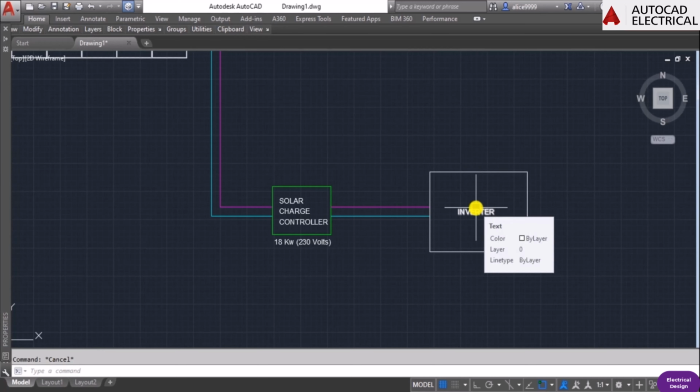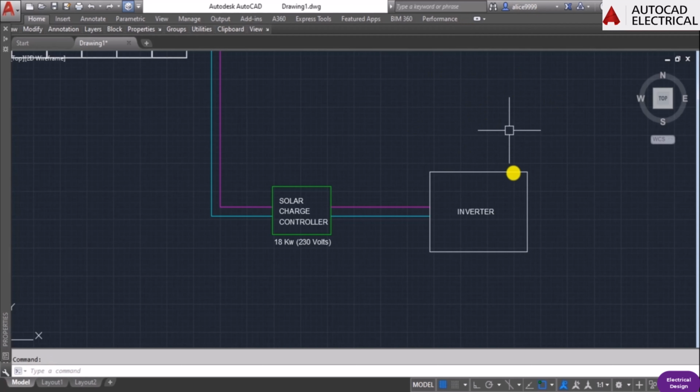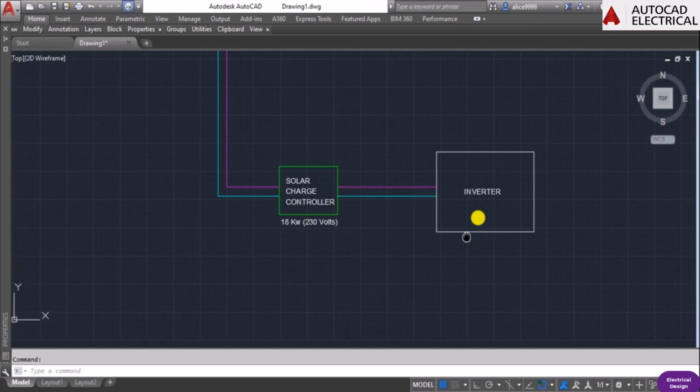Inverter sizing is a very important part. An inverter is used in the system where AC power output is needed. The input rating of the inverter should never be lower than the total watts of appliances. The inverter must have the same nominal voltage as the battery.